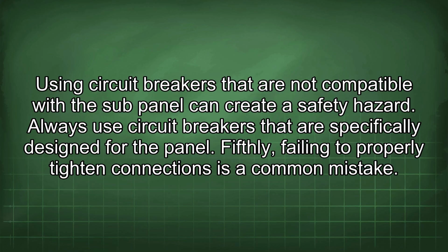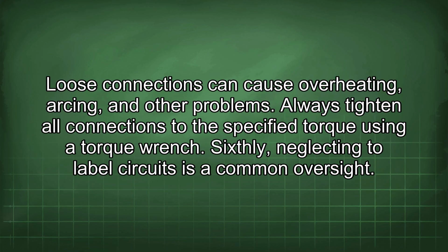Fifthly, failing to properly tighten connections is a common mistake. Loose connections can cause overheating, arcing, and other problems. Always tighten all connections to the specified torque using a torque wrench.